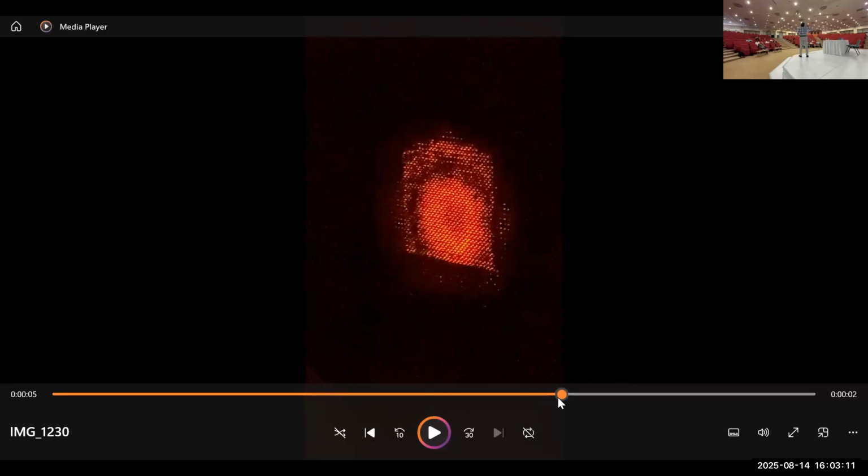So even a small noise, at the top of the pulse, or lower or in the middle, will be like a 50 kV difference. You don't even know if you have the same exact voltage, or if it's varying. So this is a lot of challenges in high voltage experiments. And also we haven't calibrated our diagnostic for probably 15 or 20 years, and it probably needs to be calibrated every year.